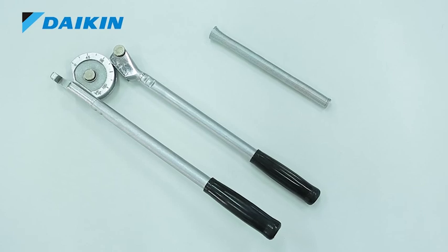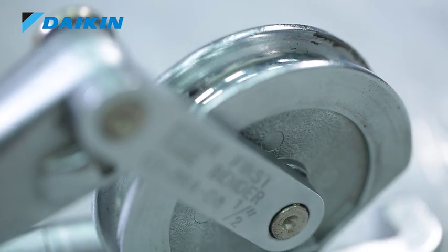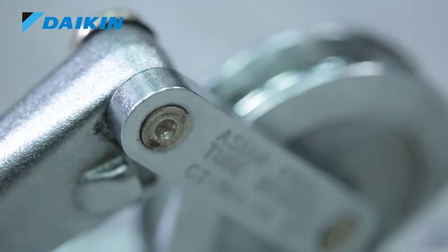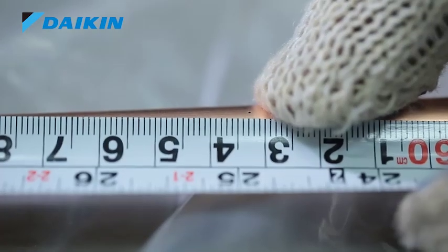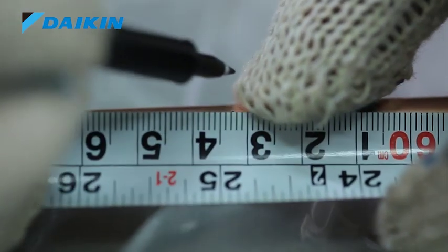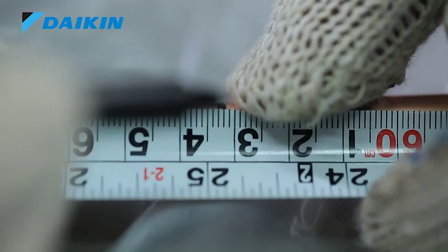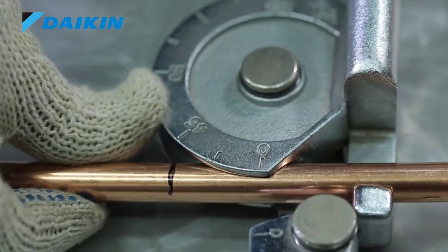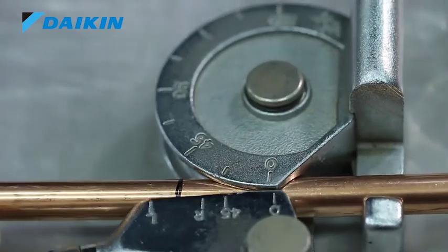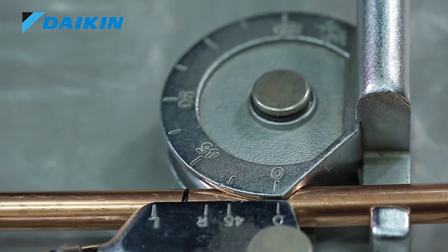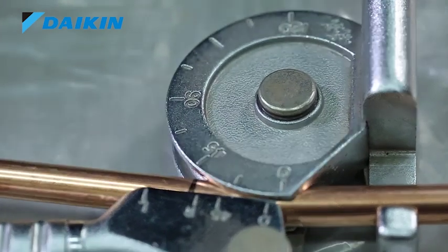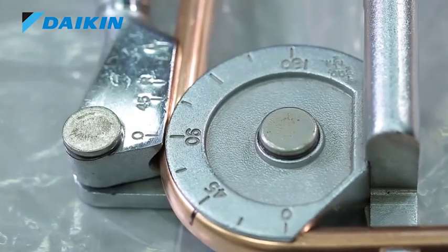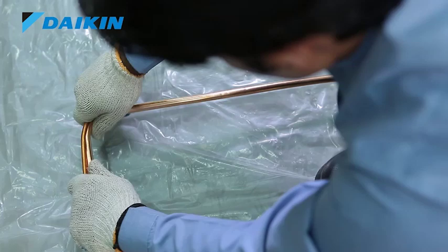You may use the mechanical pipe bender or spring bender as per your requirement. Before starting the bending, mark the point on the pipe where the bend has to be made. Then, place this mark in the bender so that it matches with the mark on the wheel of the bender. To make a 90-degree bend, rotate the bender slowly to match the wheel mark with 90. Make the bends in the piping as per the layout.